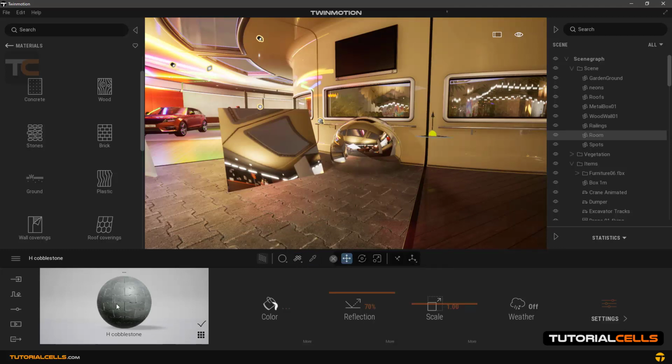There's a section in this view that shows the rendering of this material that will be changed with any change of material settings. It is a real-time renderer. Click on these 3 points to access these options. You can duplicate this material, delete it, or rename it. And as before, you can add this material to your user library. This tick mark indicates that this material has been used in the scene, I mean, given to an object.